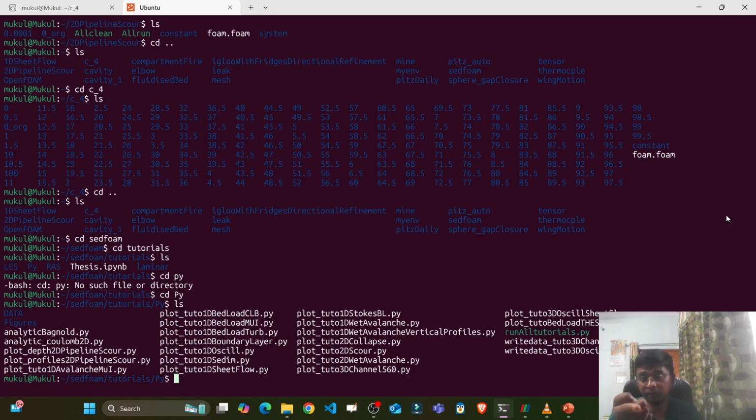The thing which I've told you in the snappyHexMesh part. If you are having a low number of processors in your machine, then it will give you a bad mesh, and if you run the same file of snappyHexMesh without making any changes on a machine with a good number of processors, you will find it completing and you will get a good mesh, the good quality mesh required for CFD analysis. So these types of things are there which you don't have any control over.